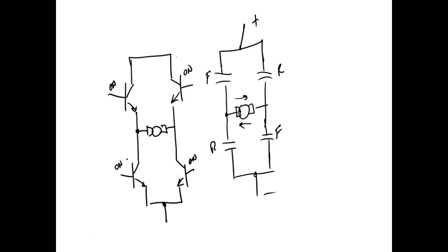You understand pulse width modulation? What we can do to a DC motor is instead of sending it DC, we can send it pulses. Now notice on these, I'm going to make the pulses at exactly the same frequency, but I'm making them bigger. Now if I pulse the DC motor with this, which one will run faster? This guy's going to run faster. This guy will run slower. So the narrower I make the pulses, the motor slows down. The wider I make the pulses, the motor speeds up. This is called pulse width modulation.